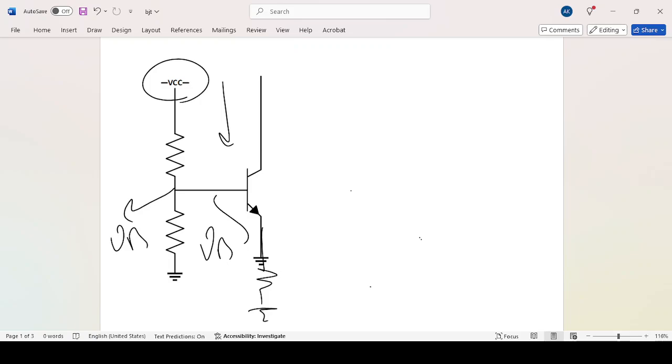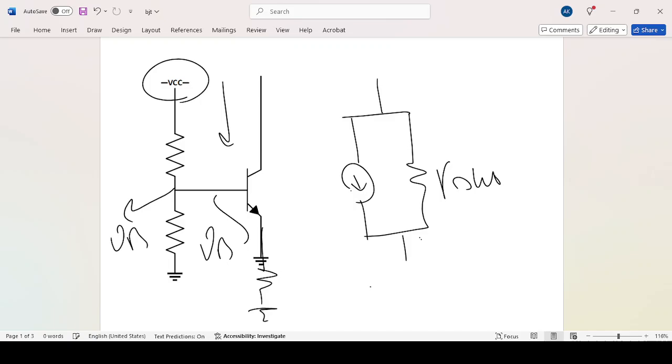We always know that we can define a current source by an ideal current source and the R out of the current source. This is a non-ideal current source, the real one that we always deal with, and we very much appreciate it if the R out is high, because when it's high, so this is, for example, V over I of this current source.